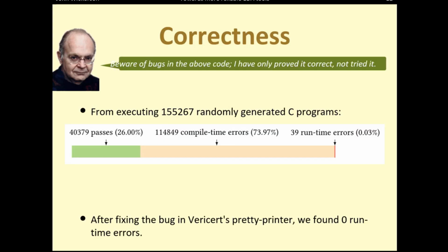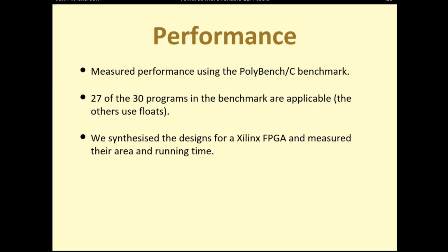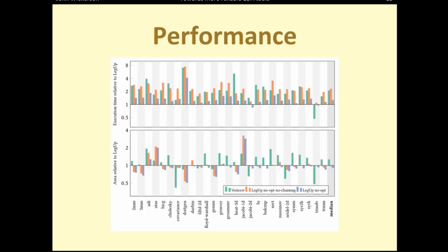But yes, sorry, Yann. He also checked performance. So we've got correctness nailed down. How does it perform? Does it generate decent hardware? We used a standard benchmark. Most of them were applicable. We synthesized for FPGA, measured area and running time, compared against LegUp, which is an open source HLS tool.